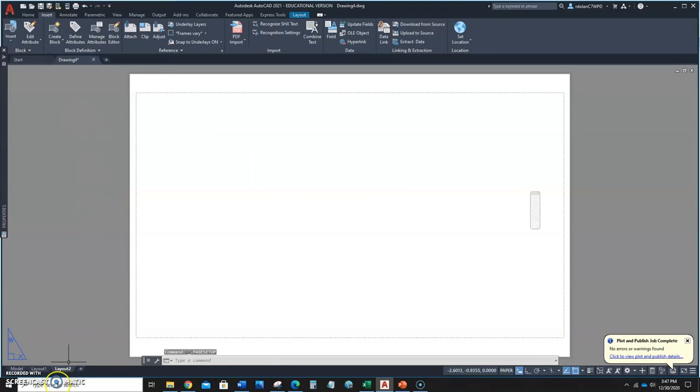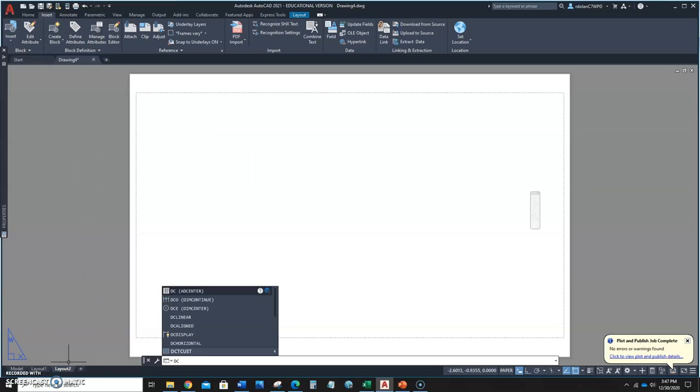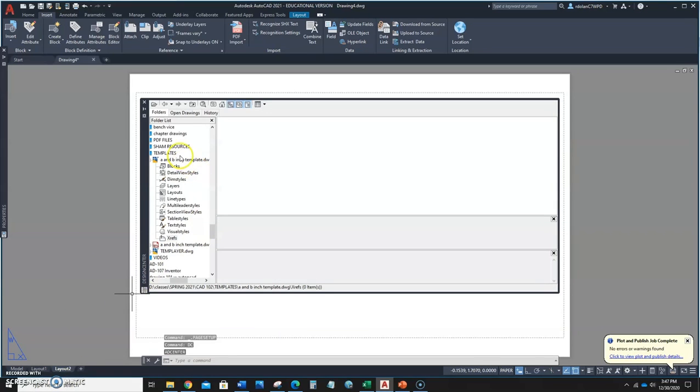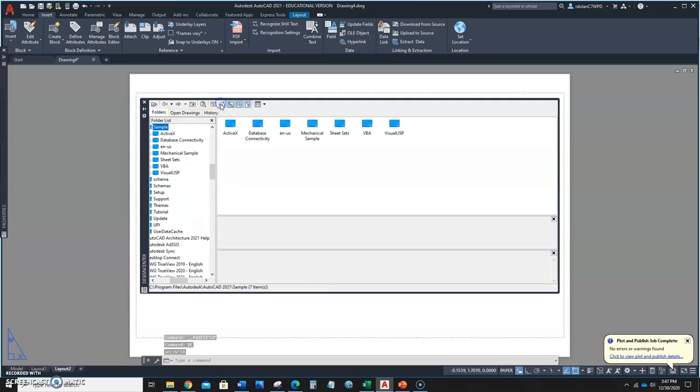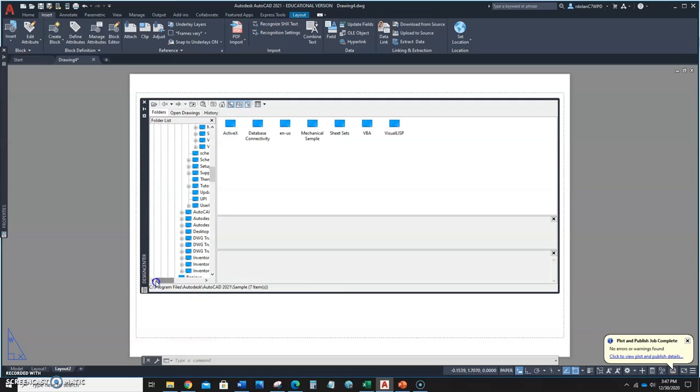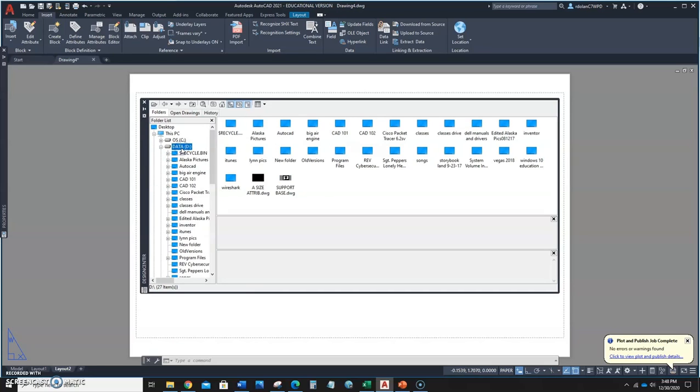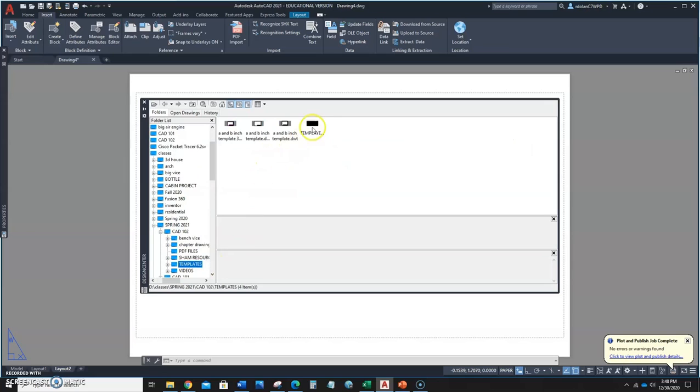All right. Now I need to use our design center, so I'm going to type DC, which will give us our design center. Now what I'm going to do is go to home here. And then I'm going to go until I find my drawings. It is mine, it's the D drive. Where's yours? Wherever you put it. And then mine's under classes, under spring 2021, CAD 102, and under templates. And here are my DWG files.